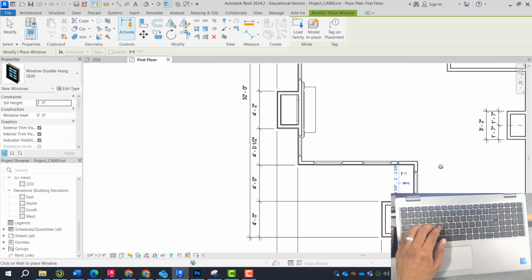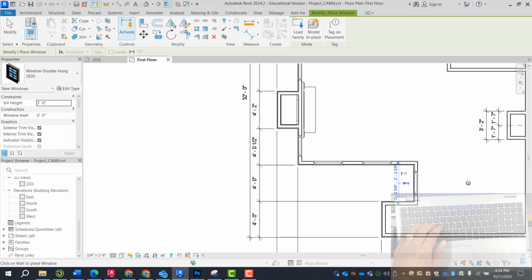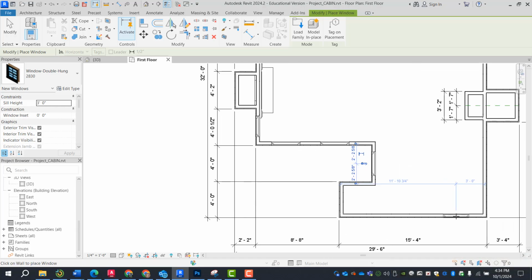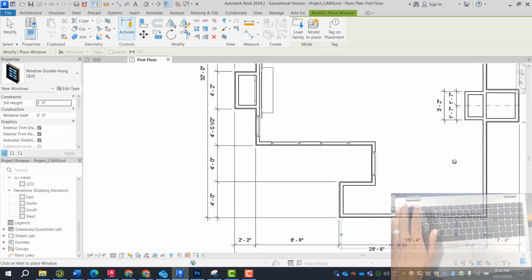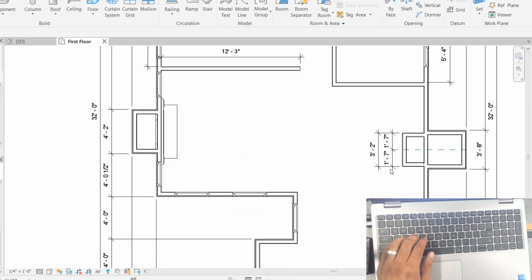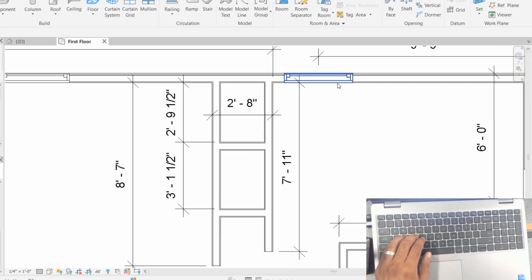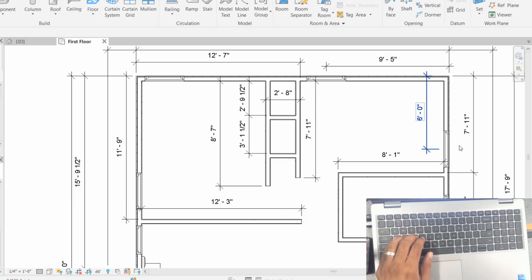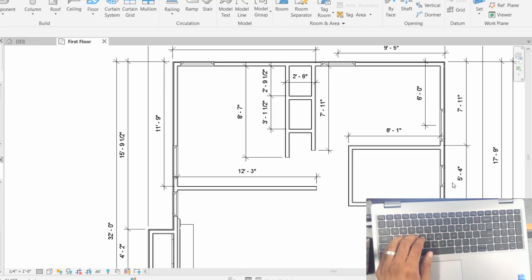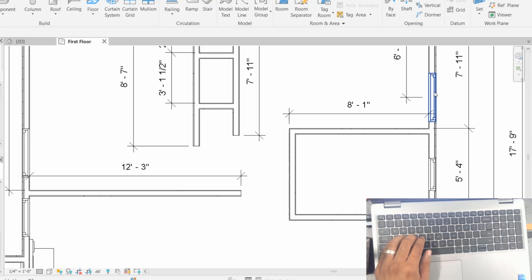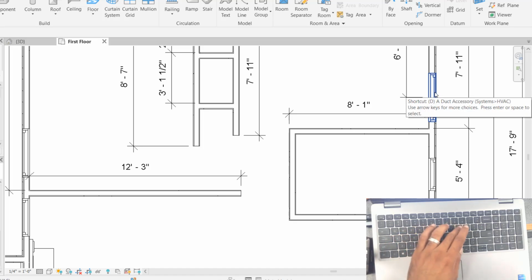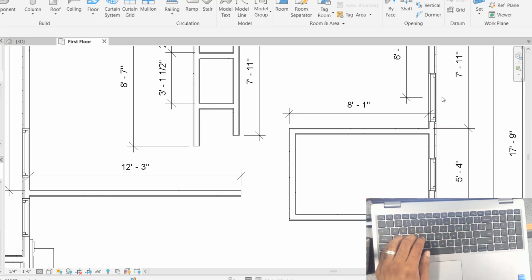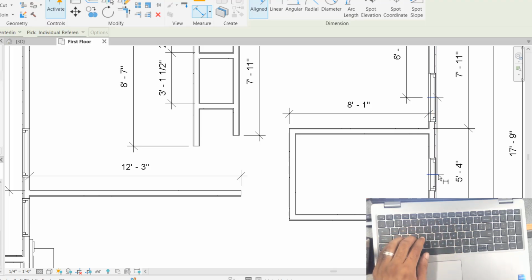It has been centering. Revit has been working for us. So I'm going to go ahead and place a window here. And that should be just about all our windows. So we had these situated so far. We placed this one right where we need to. Then this window from center to center is 4 foot 9. So I'm going to go ahead, do DI, go from center of that window to center of that window is 4 foot 9 1/4.